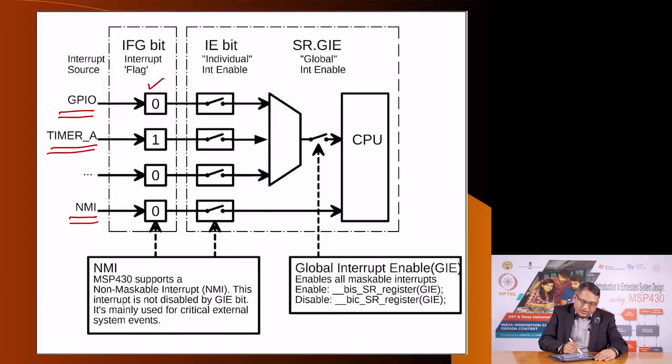Now, you see this GPIO could generate an interrupt, but you could ignore it if this switch is open. So, you have a register called interrupt enable register. If you have disabled those interrupts, this request for an interrupt will not proceed forward to the CPU. On the other hand, you see this non-maskable interrupt can only be stopped by this switch, thereafter there is nothing to stop it. Once if this switch is turned on, it can go all the way through.